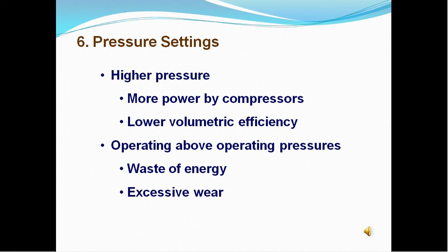For the same capacity, a compressor consumes more power at higher pressures. Consequently, compressors should not be operated above their optimum operating pressures, as this not only wastes energy, but also leads to excessive wear, leading to further energy wastage. The volumetric efficiency of a compressor is also less at higher delivery pressures.